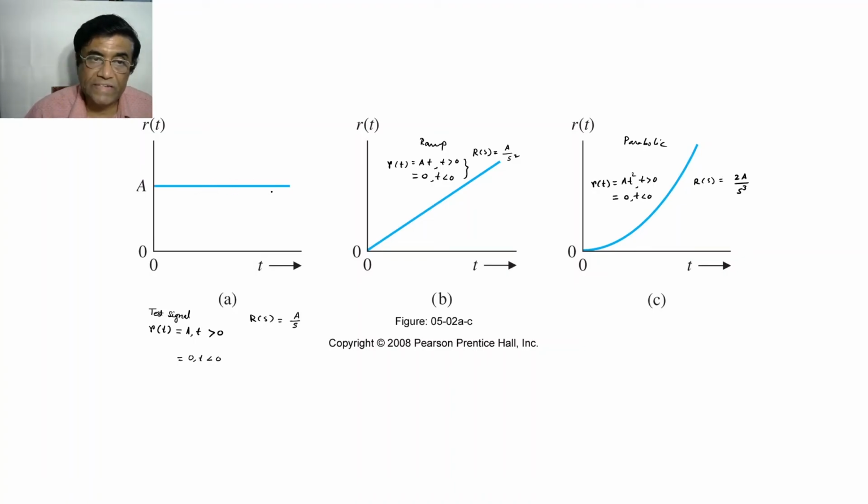So ultimately in the steady state, the controller will attain that state, based on the parameter which decides whether it will be critically damped, or if it is underdamped, how many oscillations you will allow. Okay, you will have to design in such a way that there are not many oscillations, if at all an underdamped system is unavoidable, then use it like this, so that very quickly it will stabilize.